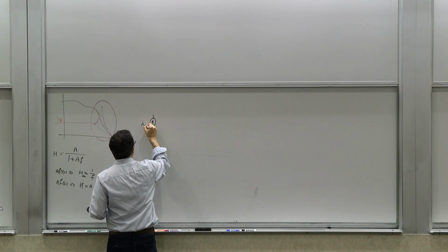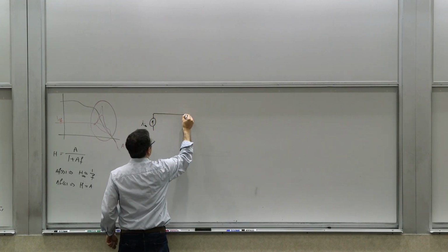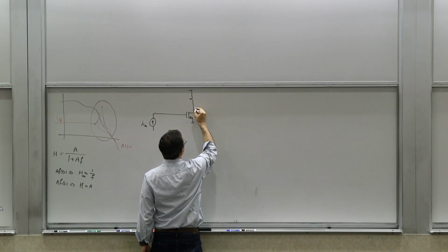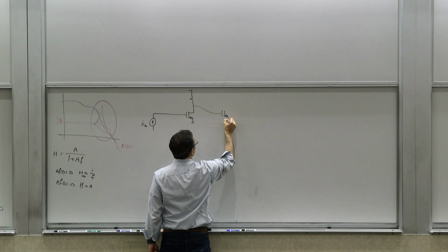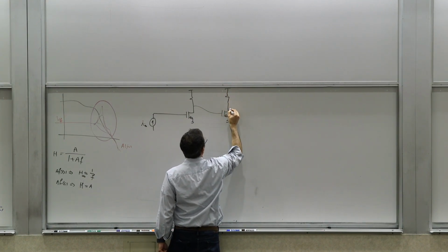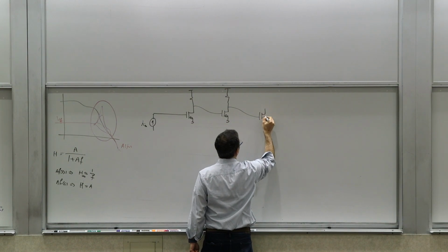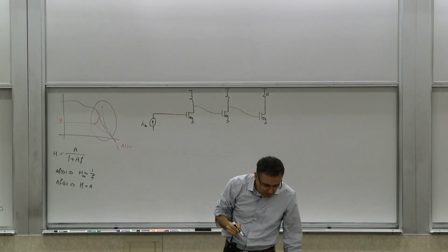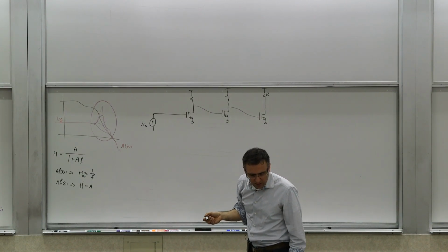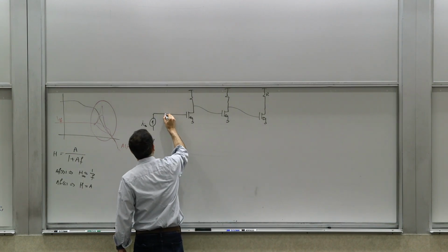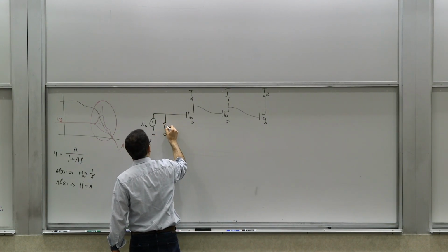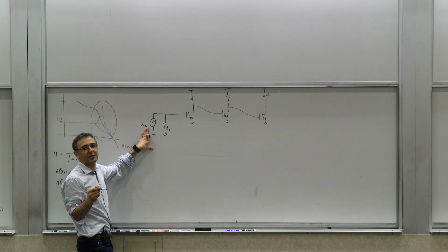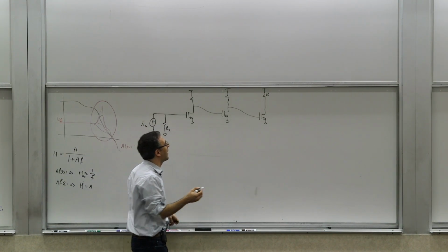So you have an I in, let's say you have a current, right? That's going through, and we are making a 3-stage amplifier. This is a very simple amplifier. We are not going into the biasing details and things of that sort. So you have 3 stages of amplification with the same load, right? So you have 1, 2, and 3, and we call these resistors R1, R2, R3. And then there's source resistance RS. This can be a model, for example, for a photodiode or photodetector in an electro-optical system. So this can be a transimpedance amplifier, for example.